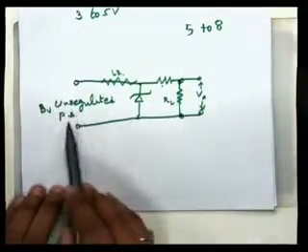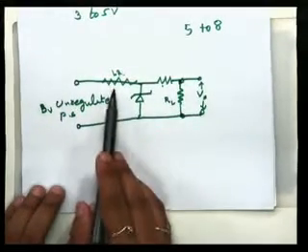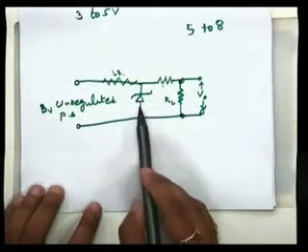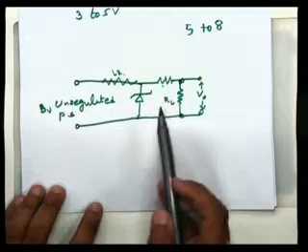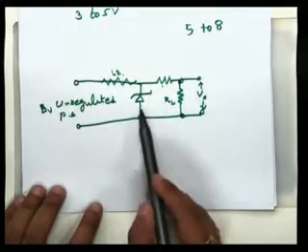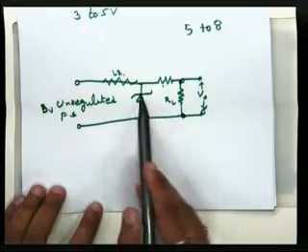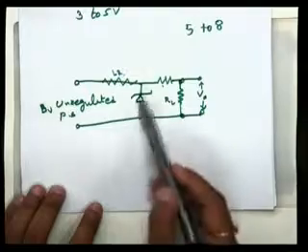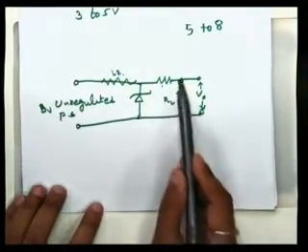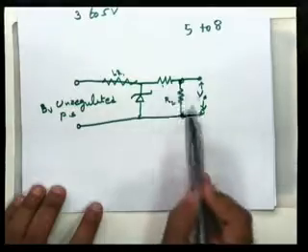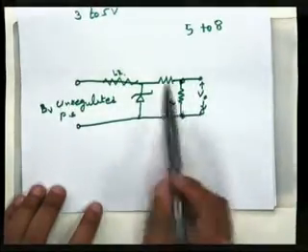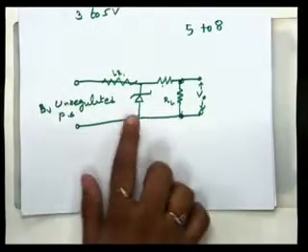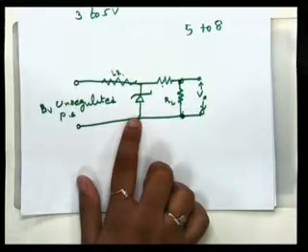So what happens when this circuit is switched on? When the unregulated power supply is switched on, this limiting resistor will resist the power in terms of the voltage it will give to the Zener diode. Here we have used a 7.5 volt Zener diode, so at 7.5 volt of reverse bias voltage we can get a large amount of current in the circuit, and due to that there will be a voltage drop across RL. If we measure the voltage across RL, then we can have a constant regulated power supply. The excess voltage drop is taken by the Zener diode itself.